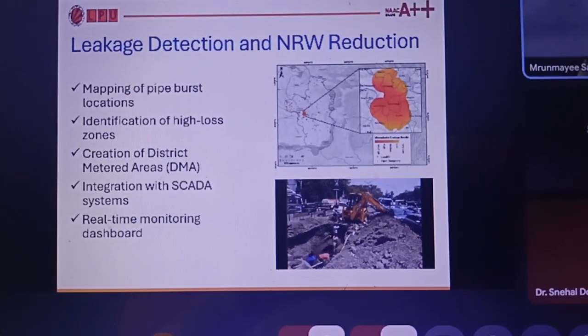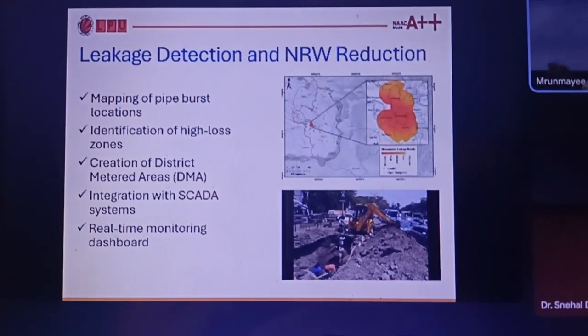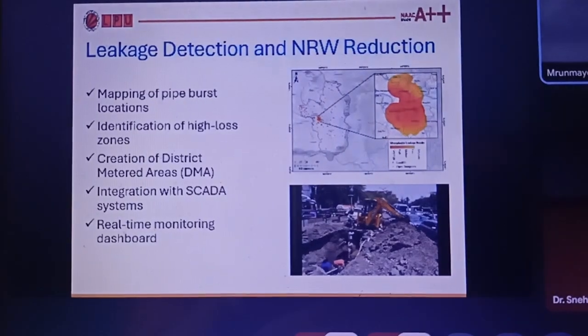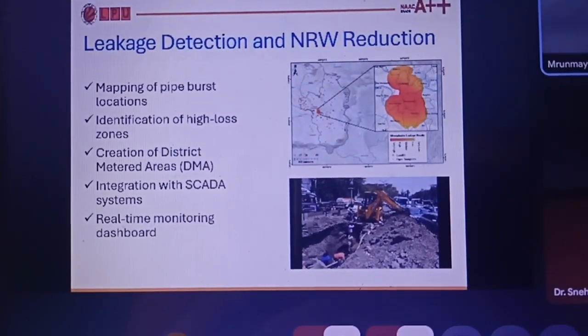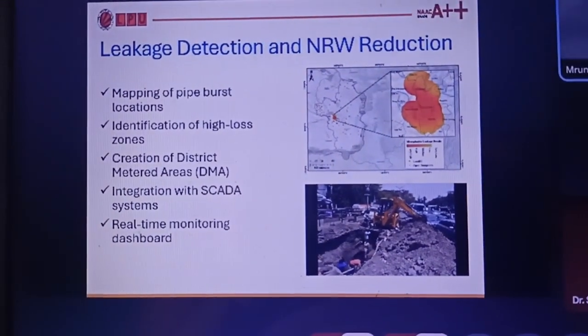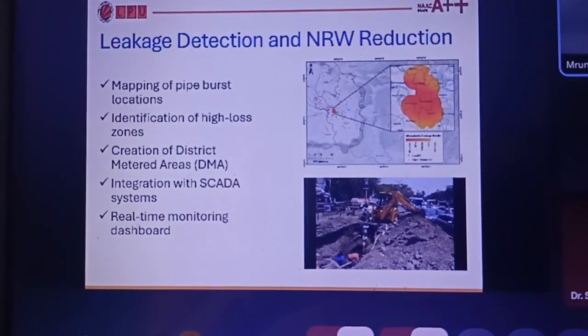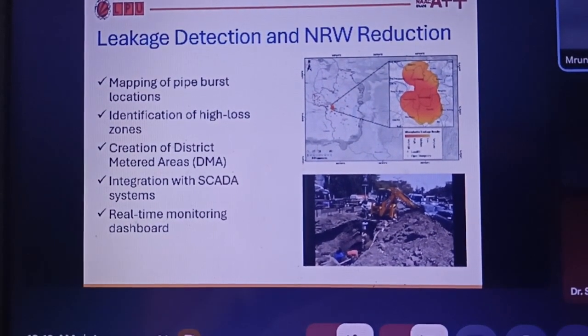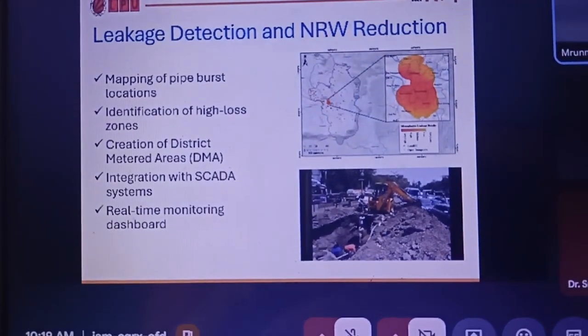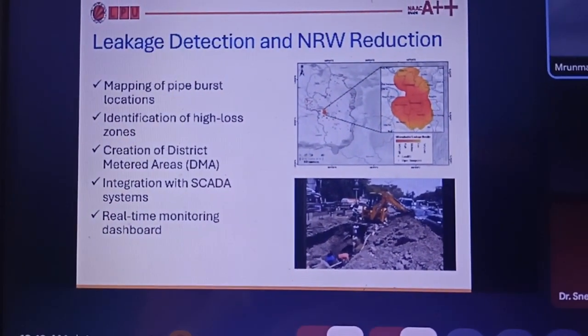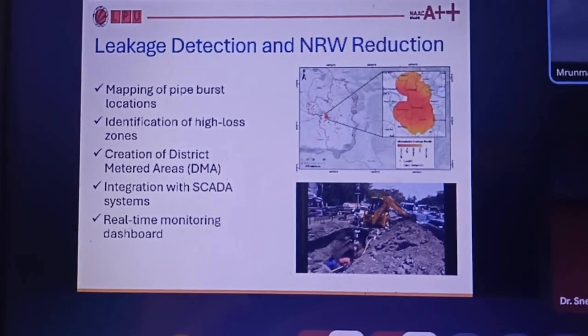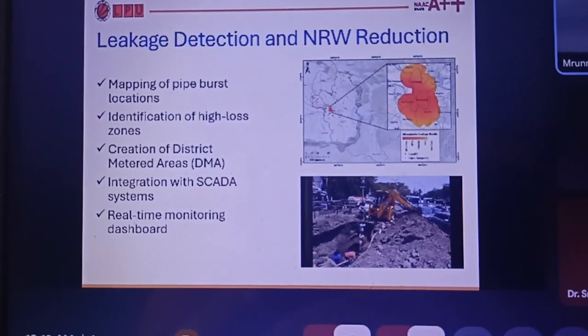If we permit 135 liters per capita per day, and you say that in your house you have 5 members, we have supplied you approximately 800 liters of water per day. If you are exceeding beyond that, you have to pay according to the meter. So that is again a grading pattern which is implemented in India and also in many countries.